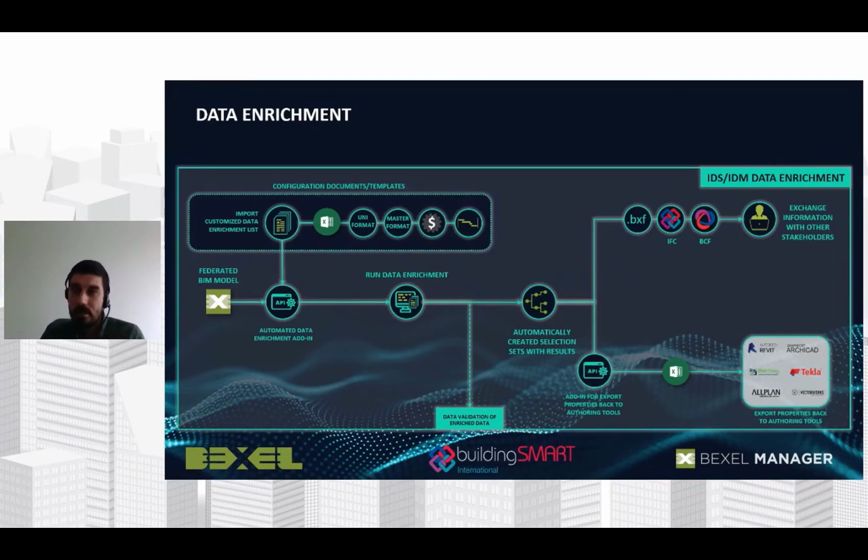So let's just give a simple example. If you know that certain elements are of the category wall, if you know that those elements are on specific floors, if you know that those elements are structural or not structural, you are more or less able to define into which category in some standardized cost classification or project classification in general you can put them. And you can specify these rules and use them in all future projects without the need to ask designers to populate this classification data manually.